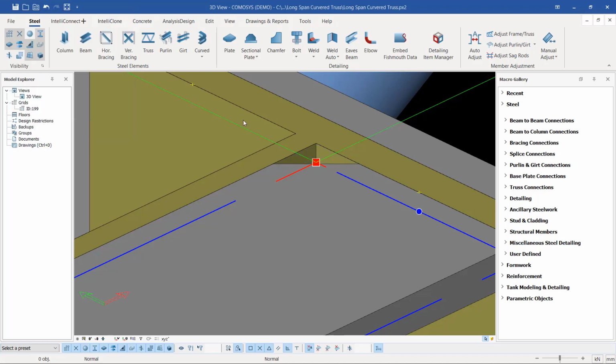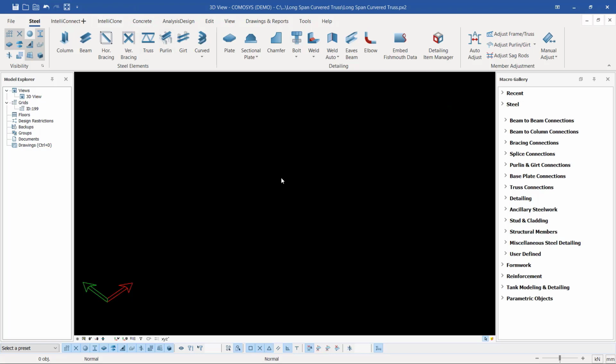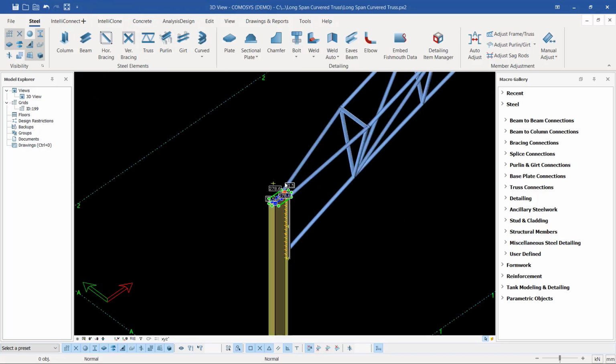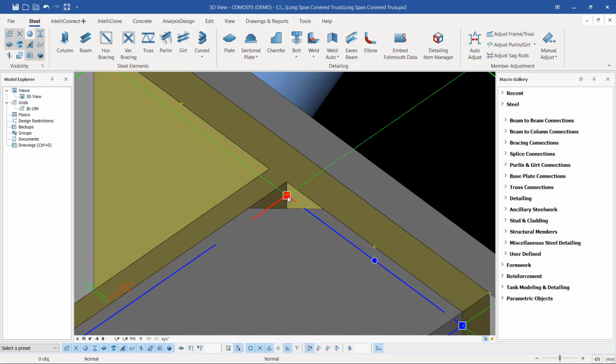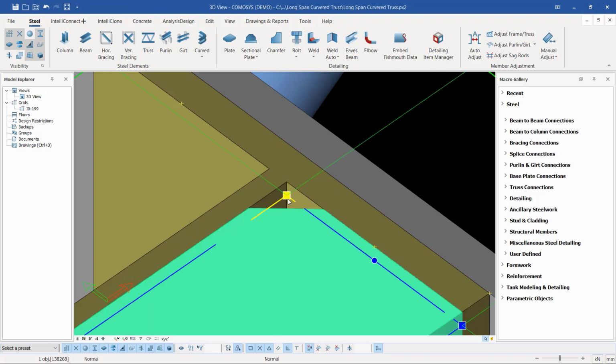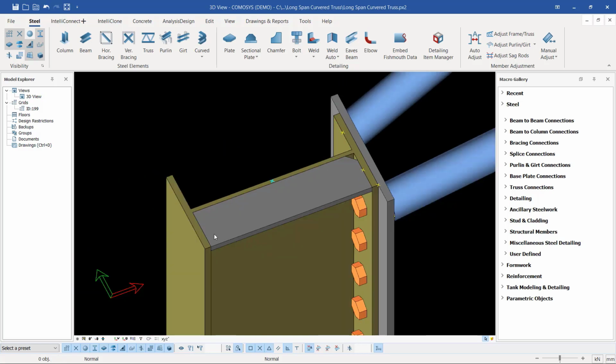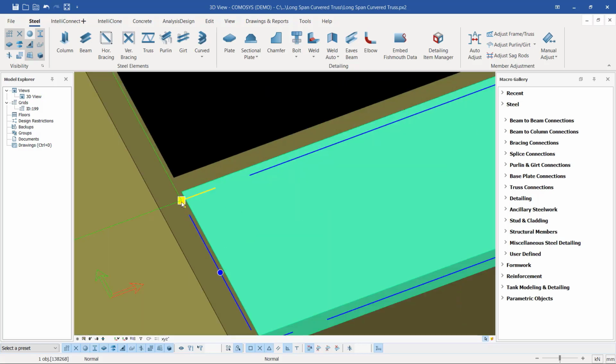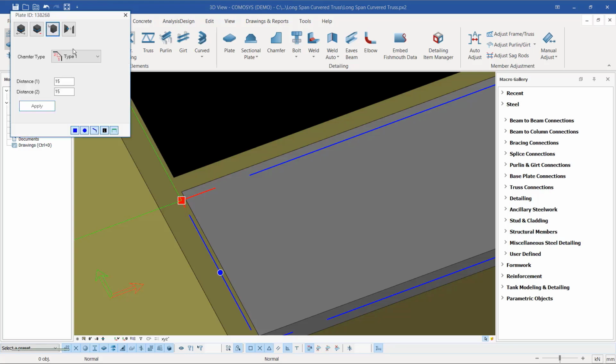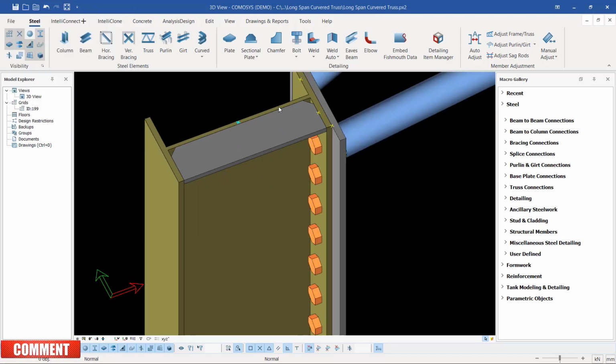If you take a look closer, you will see I have my chamfer already in place. If you zoom closer, you'll be able to see it. If I turn that round like that, you can see I have my chamfer in place right there. I'll apply the same on this end. I'll click on that, come to chamfer and apply chamfer on that end, then click on empty screen, and I want to mirror this to the other end.